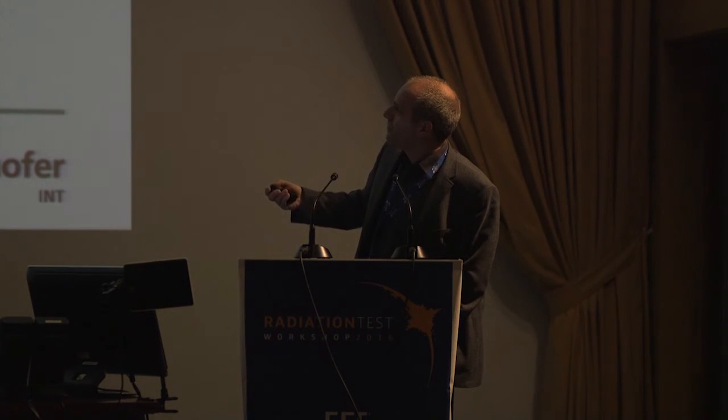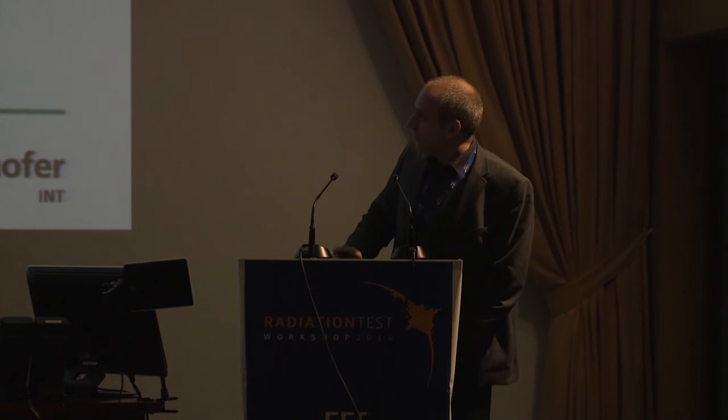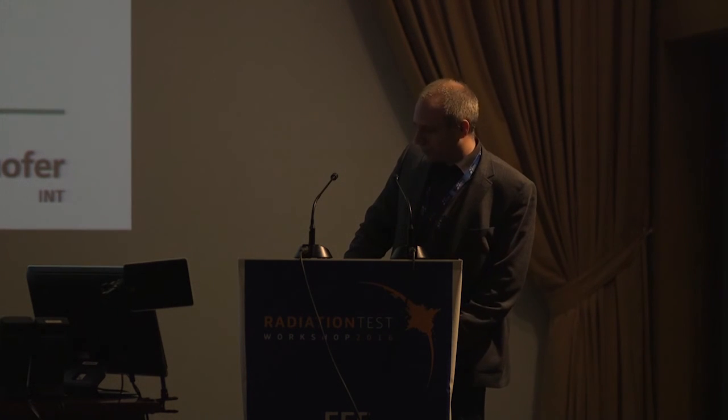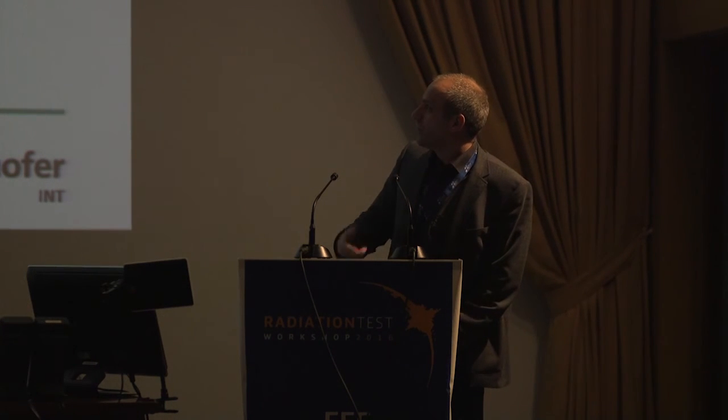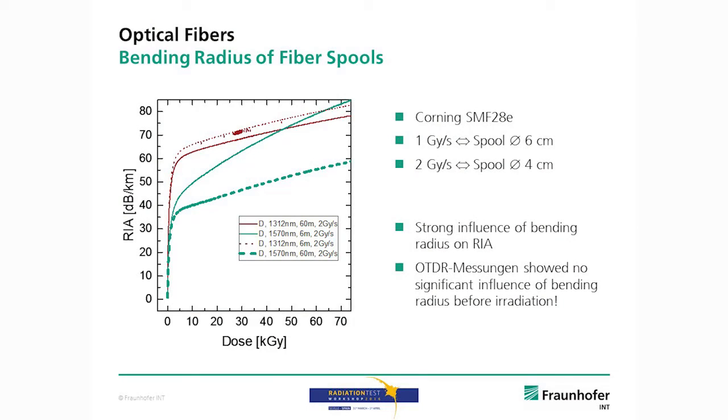Usually, people tell you that below 1 microwatt there's no effect, which was here. And it was thought that this effect was not as important anymore with newer fibers which got better quality. But the recent measurement in our lab shows that this still is a problem. And so you still have to be careful about the light power in your tests.